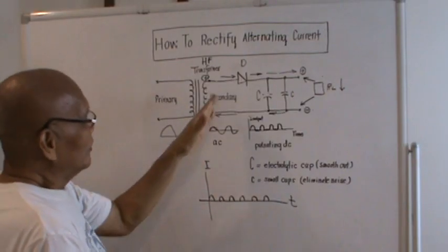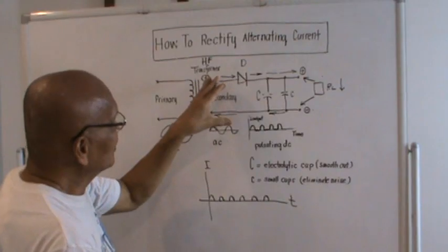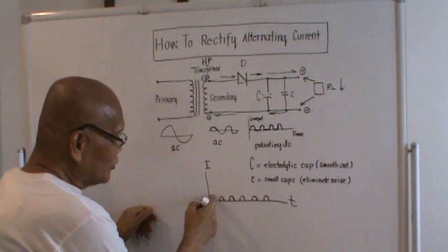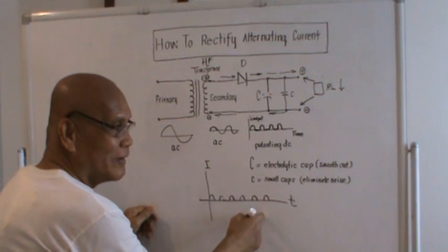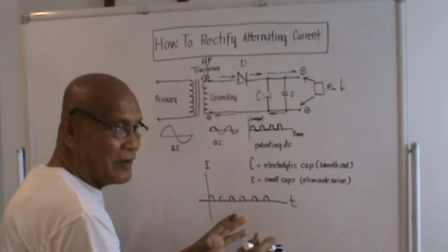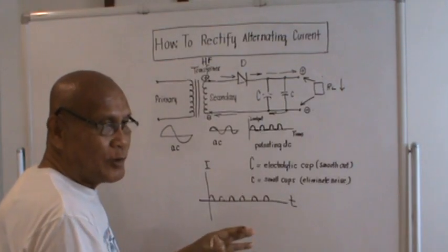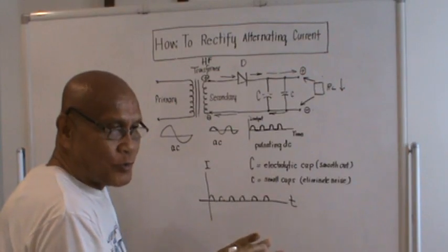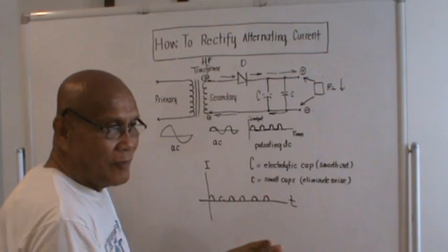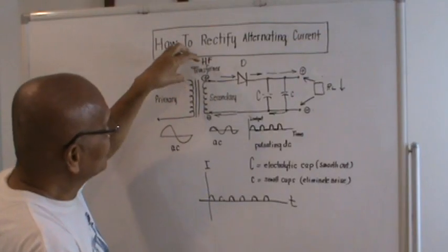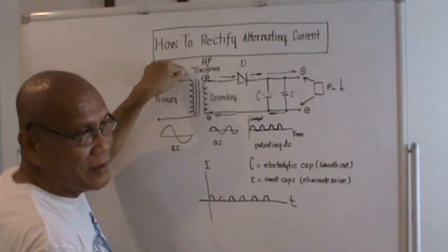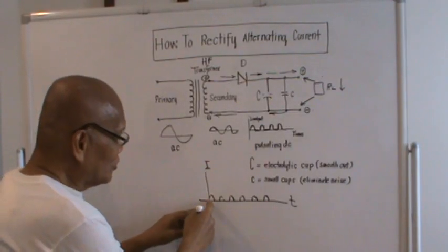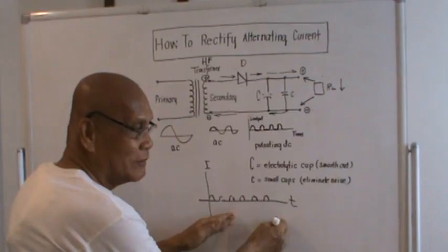So, if the frequency on the secondary side will be in the range kilohertz and megahertz, these pulsations will be very smooth. It is smooth. You could not hear any humming sound. Okay? So, for switch mode power supply, instead of using the so-called 60 Hertz transformer, we use the so-called high frequency transformer so that the pulsations of the output will be smoother.